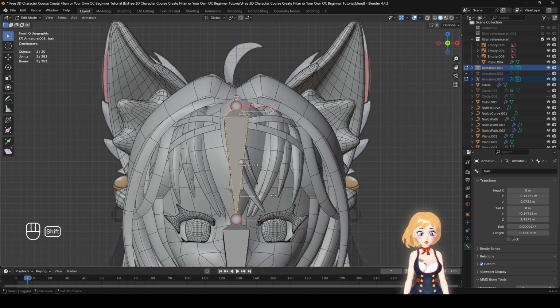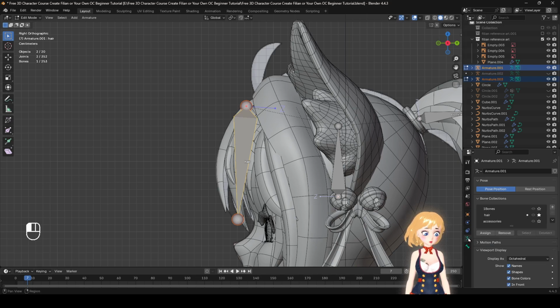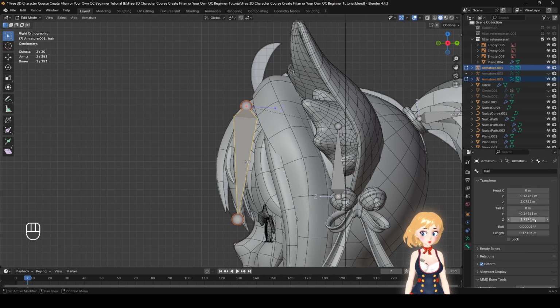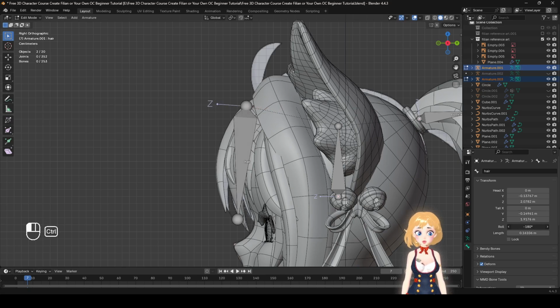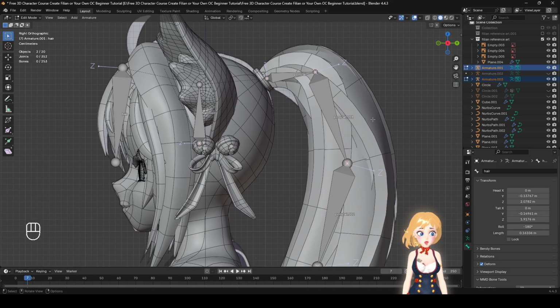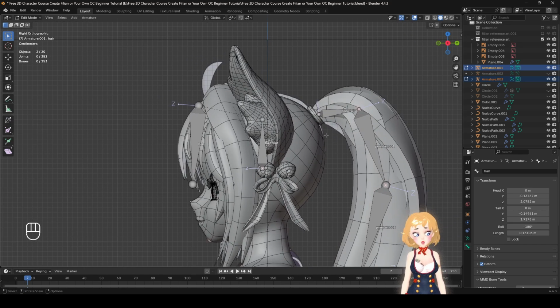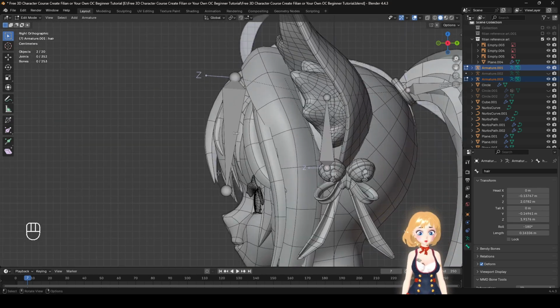And just make sure to duplicate it. Before you duplicate it, I want the Z on the outside. So make sure you click on the bone right here. Let's see, is it this one? Okay, it's roll. Hold Control. Do it exactly at the Z or close to it. You can type in the number you want. Inside VRChat, it has a special feature where the bones are for it not to go in and out. So I recommend to have the Z always go in, or any number. It could be the X that always goes in and out. It just depends.